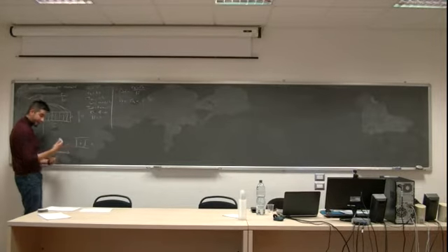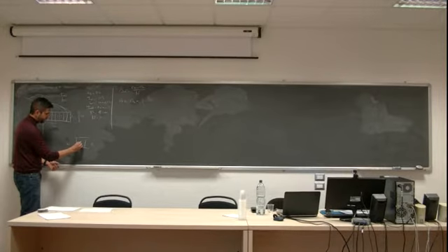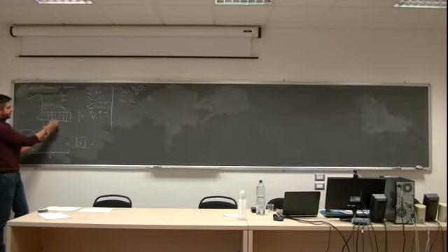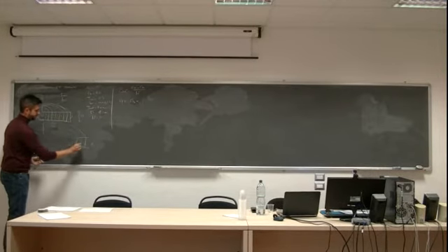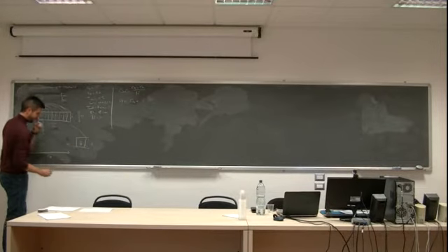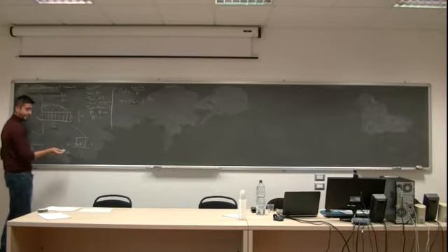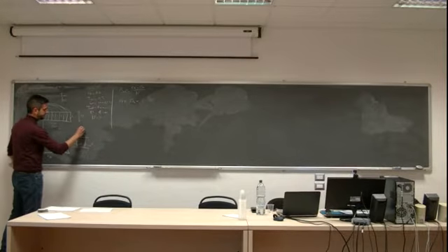Now, because I will have to compute conduction between two nodes, I will have to compute the surface between two nodes. If I'm looking at node number 4, imagine, number 4 will receive conduction from the west, will provide conduction to the east, and it will dissipate convection.